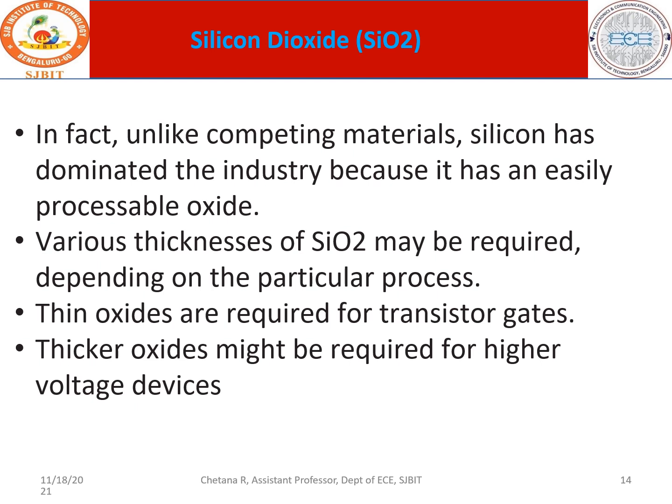Normally at the source you give ground potential, and at the drain you give your supply. So at those regions you are giving voltages, and to give those voltages you need an appropriately thicker oxide. As I told you, the thicker oxide dimension is 1 micrometer. I hope I am clear with this topic.